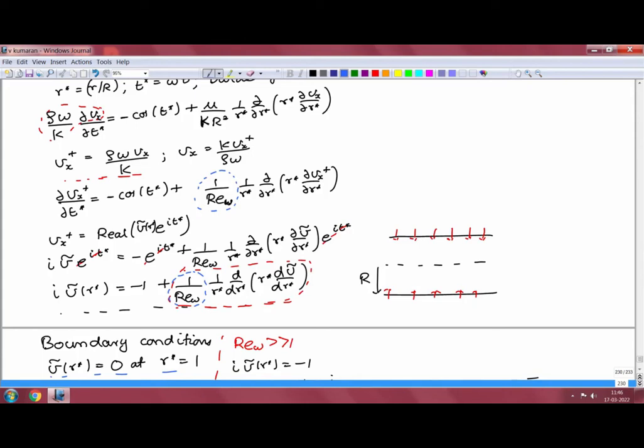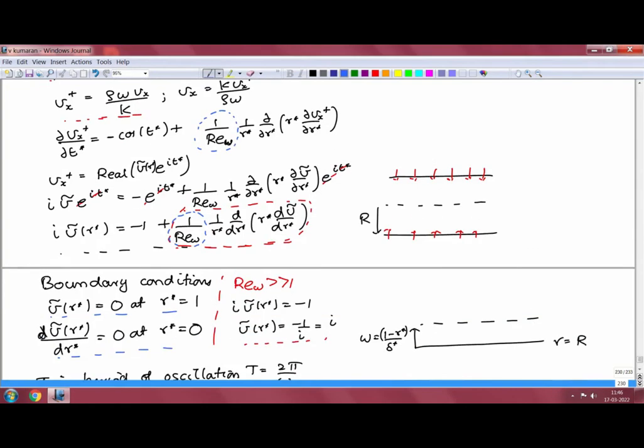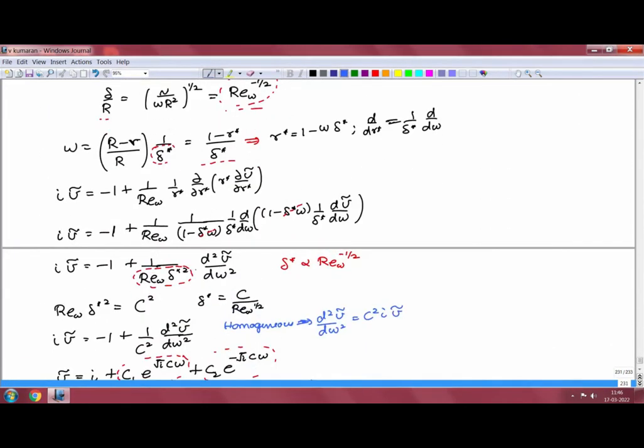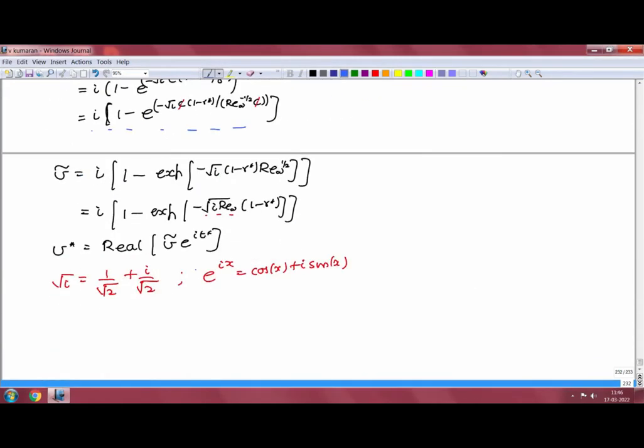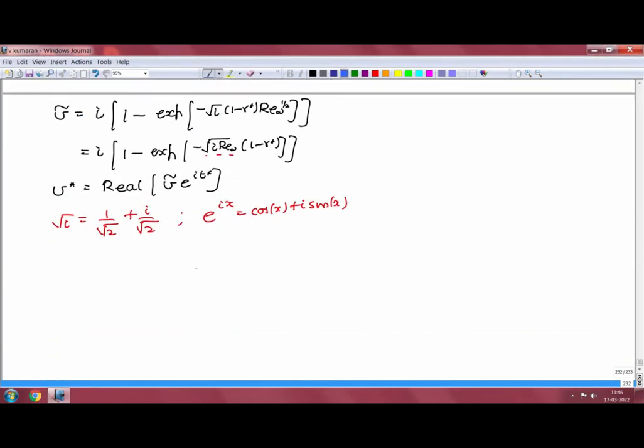Therefore, the solution of the complete equation in the limit is not the solution of the simplified equation where you neglect the term that multiplies the small parameter. And for that reason, these kinds of solutions are called singular perturbation solutions. And it is necessary to postulate a thin boundary layer close to the surface where the velocity decreases to 0 in order to obtain the accurate solution of this velocity profile.